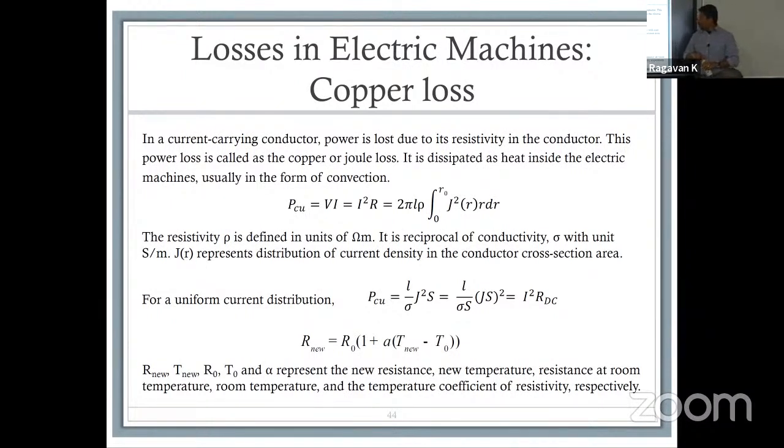So in terms of the uniform current distribution, one thing you have to remember is that as your temperature changes, so does resistance, because your electron mobility changes. When that mobility changes, you also have to account for it if you have variables in your system, let's say you're doing sensorless control and you are assuming a certain Ri plus L di/dt equation. If your temperature in the system changes quite substantially, then your R is not going to be what you thought if you are measuring at 25 degrees Celsius versus, let's say, 95 degrees Celsius. Let's say you're going to peak power for traction. Your R might change, which means you have to have an awareness of what happens.